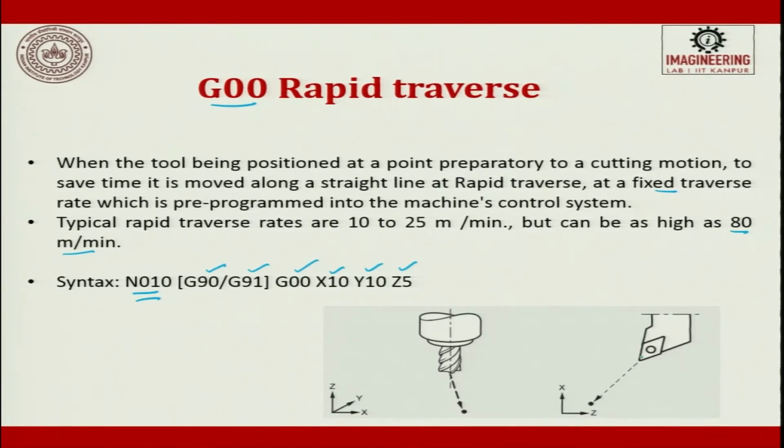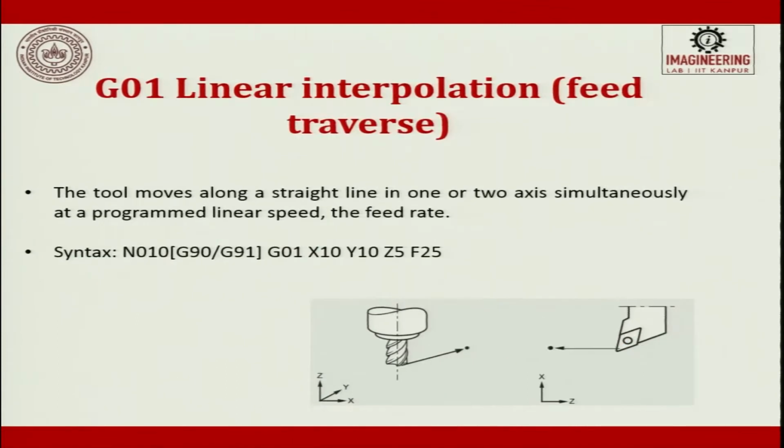When we do this on a turning machine, it can be with respect to the nose radius, which you have to define beforehand, or with respect to the center of the tip or the periphery of the tip. Depending upon the tool register, you change the center point accordingly. You have to look at how the machine takes the reference points. If they take it for the periphery, then you have to give these points as offset. If you take it for the center, then the diameter or the radius is given as offset.